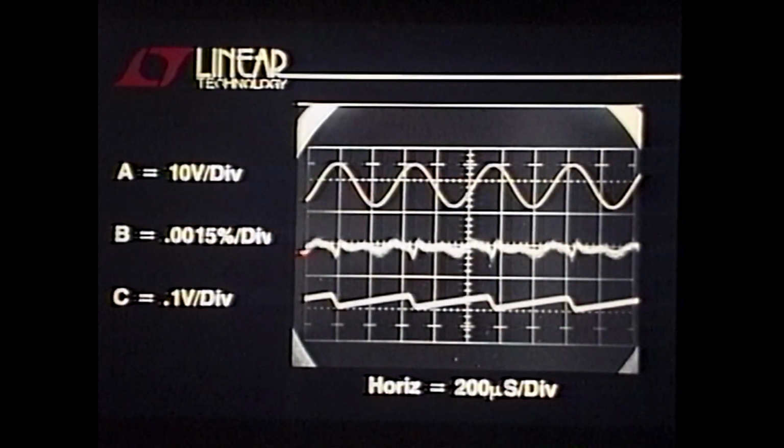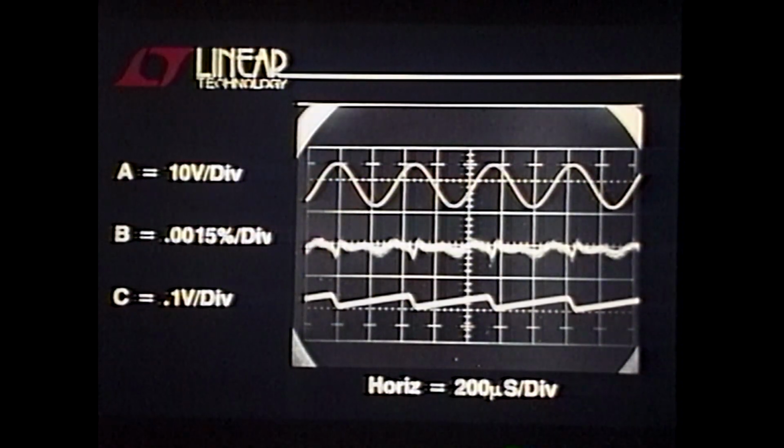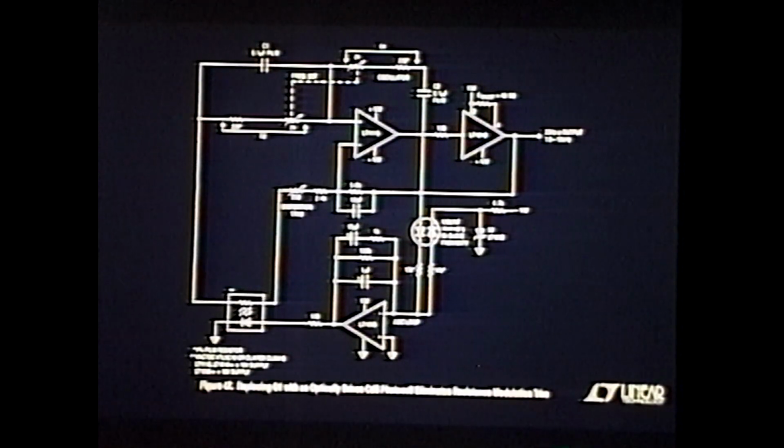Now you take a hard look at this problem. You're down to 15 parts per million distortion. You can see some of this stuff here, but most of the power in this distortion waveform still looks like it's kind of following a 2F outline. If you want to improve on this number, the key is right there. Where is that 2F getting in? You go back and you stare at the circuit.